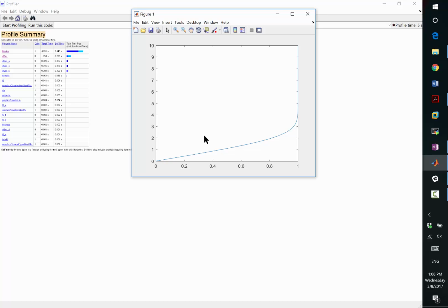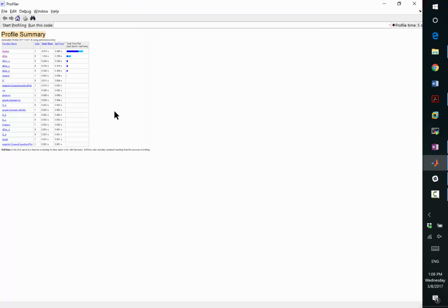We are going to do two things in the beginning of this lecture. One is to look at whether there is a way to solve it faster, and then to probe the solution to see the balance of terms. The pressure term, u_e times du_e/dx, has to balance the x momentum transport term outside of the boundary layer, plus the dissipation term, which is the y derivative times the kinematic viscosity times the second order derivative of psi.